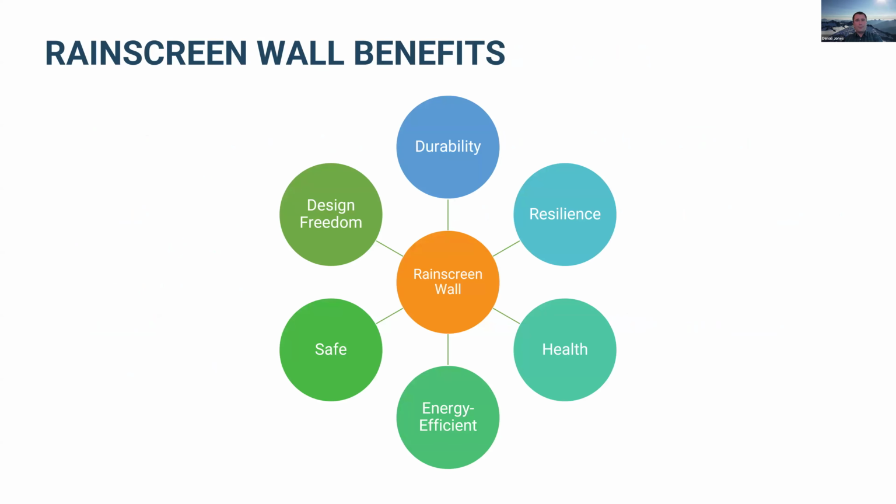So the benefits of a rain screen wall, there's many of them, right? And I would say the biggest one is just really durability. So we're increasing the longevity of the structure and the enclosure components. We're avoiding premature replacement or excessive maintenance. We're reducing costs for owners by managing that water effectively. It's going to make a more durable, longer lasting building.